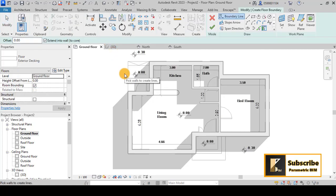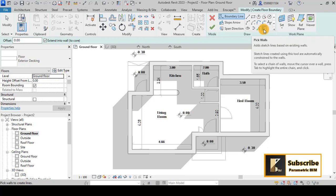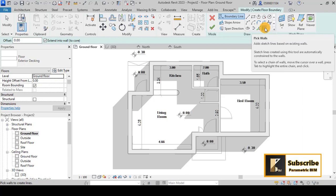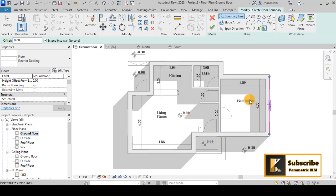Once you choose that, you have the opportunity to draw any wall, but because we have walls or lines, we can pick lines or pick walls. And this is very important because when you have a section, you have to extend your floors to the structural element of the walls. So I will go with big walls, and now pick these walls like that,